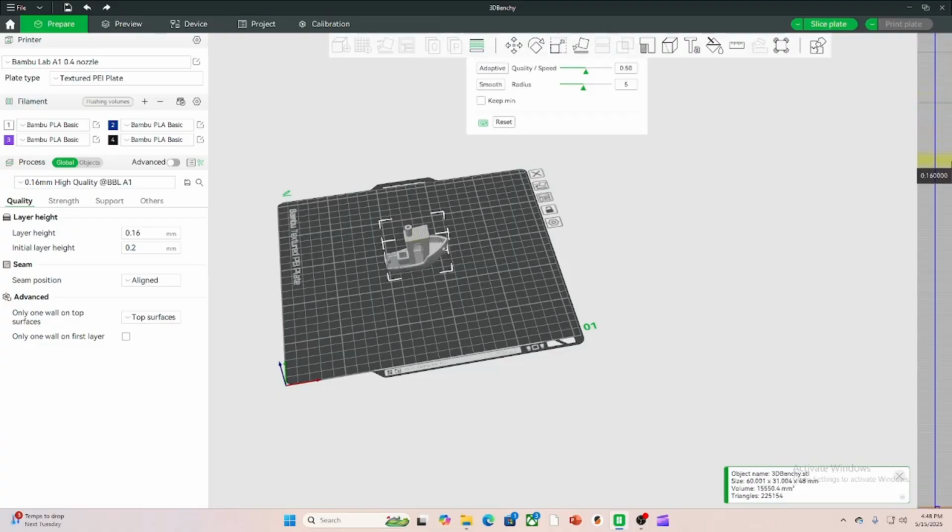Variable layer heights, you can choose your layer height. Your 3D printer will do one layer at a time from the bottom to the top. This will allow you to adjust how thick those layer lines are. When you get done with your print, the smaller layer lines you have, the less you're going to see divots and other areas that are deformed on the outside of the print.